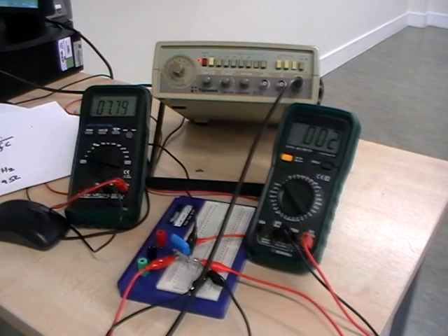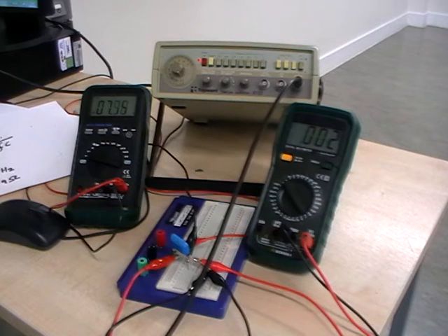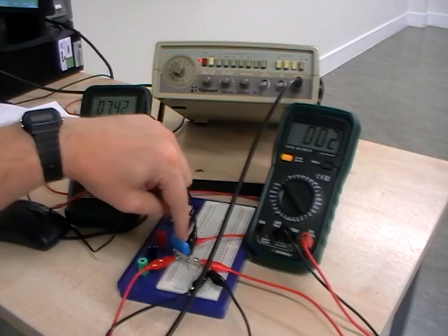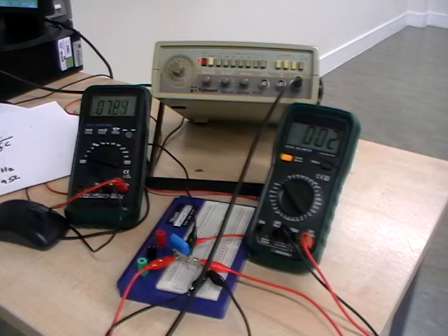And here we've got 2 millivolts. So what we can say is, the capacitor has got a very, very high resistance. Yeah? So at least 1,000 times higher, it's about 2,000–3,000 times higher than our 150 ohm resistor to drop most of the voltage and only allow the resistor to drop about 2 millivolts.